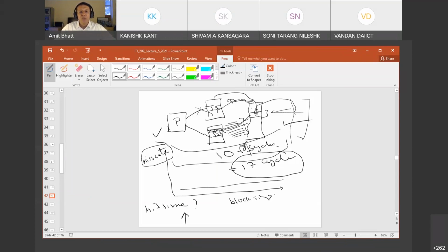But then it's not a great idea. Someone may complain that the processor will have to wait for 10 cycles while the memory management unit goes and fetches this, plus additional cycles if the block is too big. I brought it over here and then the processor wrote it. So the processor was idle for 10 cycles or more.